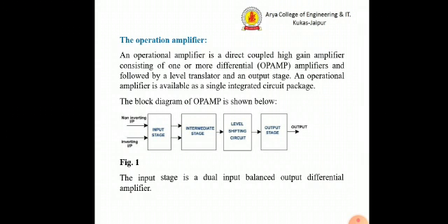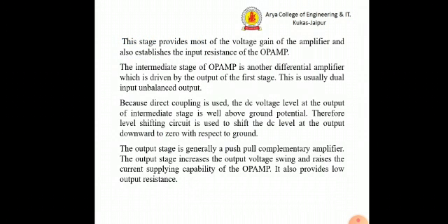The last one is the output stage. Basically, this output stage is a push-pull complementary amplifier, and it increases the output voltage swing and raises the current supplying capability of the op-amp. One of the features provided by this last stage is low output resistance.